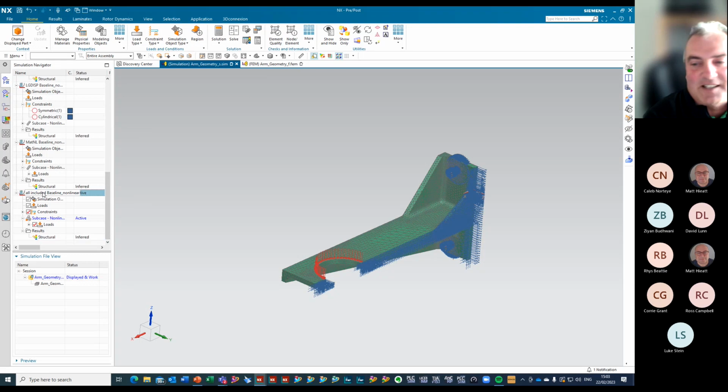Well, you've got the data and you've seen the process that I go through. So you could vary the load. You could just try different loads and see what effect you have. But at least you've got some loading types where you can see what the behavior is. If you went much higher, then you'd actually see the bracket buckle. If you put a much higher load onto it, you can see the bracket literally start to buckle at a certain point. And you can do that assessment.